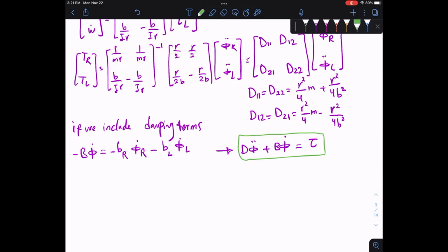Now, if you want to control this, usually we use a PID controller for DDRs because of the DC motor. And what are we controlling here if we develop a PID controller? So the variable here is the velocity of each wheel, right? We control that through controlling the DC motor, right?